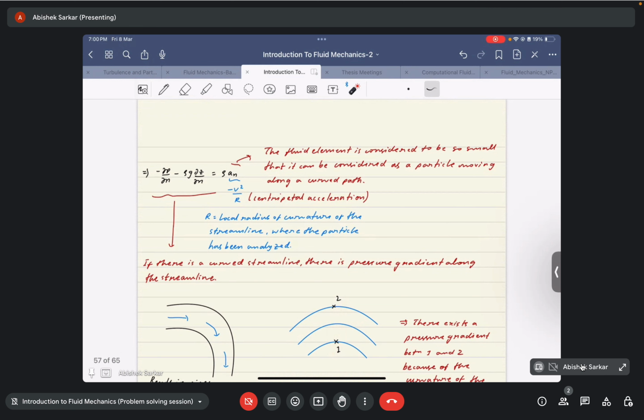So you may wonder why we want to consider this term. If we consider it to be a piezometric pressure, let's say p star is equal to p plus rho gz, then if we take the derivative along the normal direction, we will get this expression. So the piezometric pressure varies if there is a curvature along the streamline, which is given by this equation.